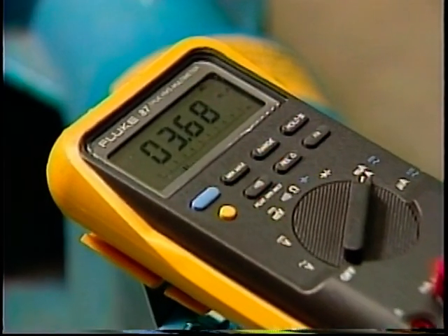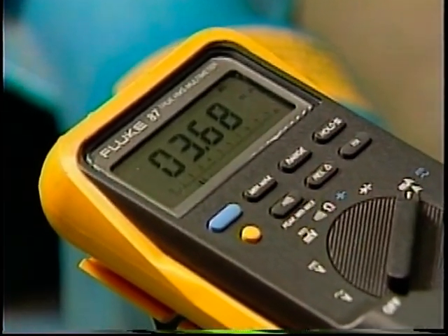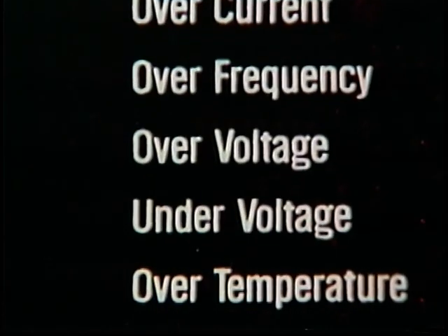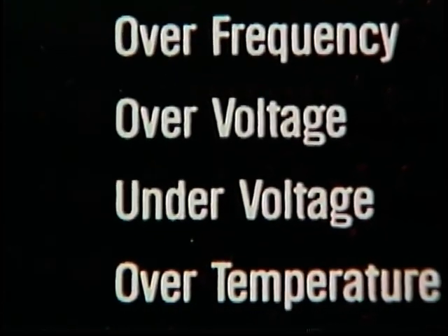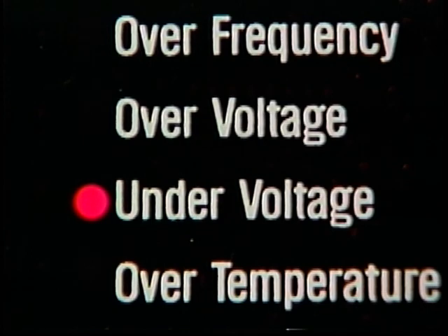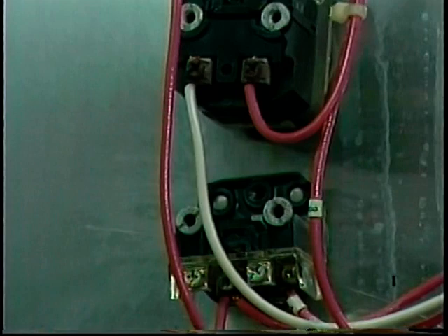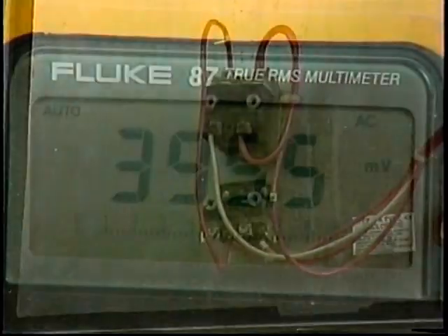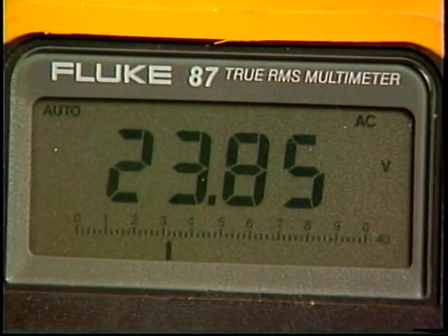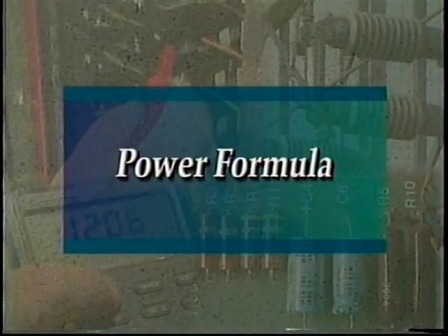Likewise, if in the same circuit the measured current level is lower than normal, the troubleshooter knows that the circuit resistance has increased or the circuit voltage has decreased. This information can be used to determine potential problems such as dirty switch contacts, loose connections, or a low voltage condition.